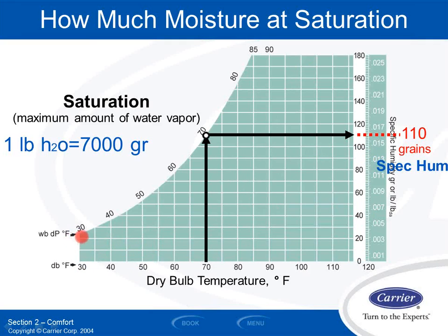This one curve here along the top side, that's my 100% relative humidity curve. There's no chart to the left of that, because to the left of that, my air would be fully saturated, and I'm not going to be adding any more moisture to that air. So the chart just doesn't exist on that side for psychrometric purposes, for air purposes. So once I get to that line, I cannot continue to add moisture to it. I realize there are things such as supersaturation, but for HVAC, that's not part of our realm. So we're just going to stick with that side of the chart not existing.